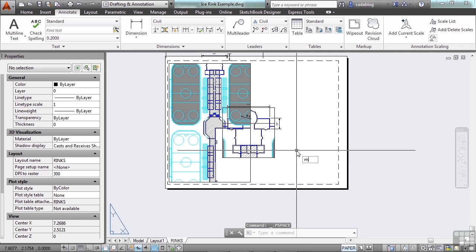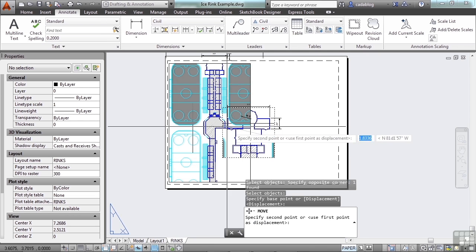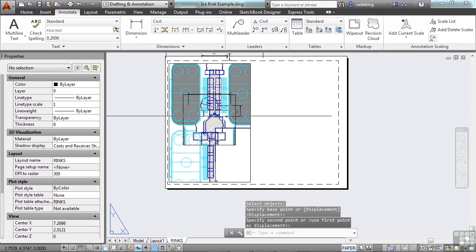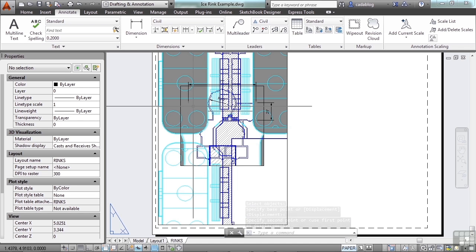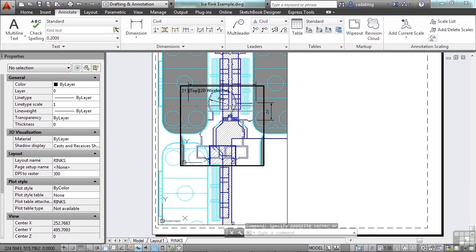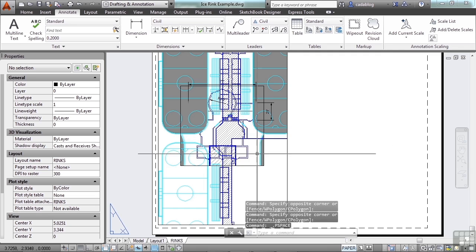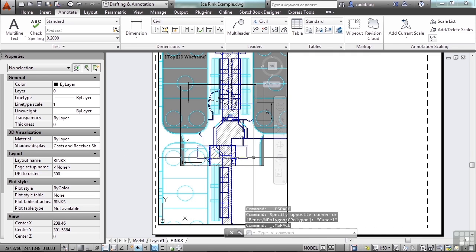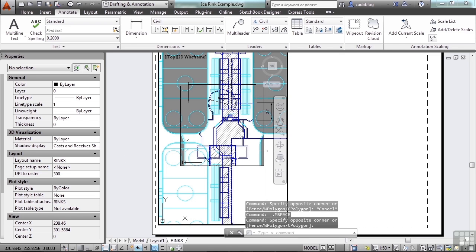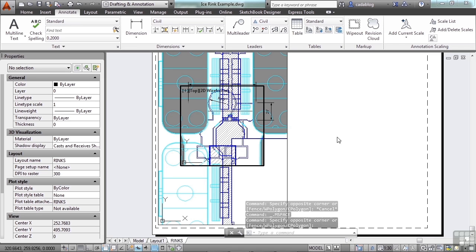Let me show you another example. If this viewport is completely inside the other viewport, which happens sometimes, and I click right here, how do I get that viewport? See, you can get stuck real easy because I'm inside the viewport. So if I click outside and then I click inside again, I'm not getting the right one. So I press Control R and now that one's activated.